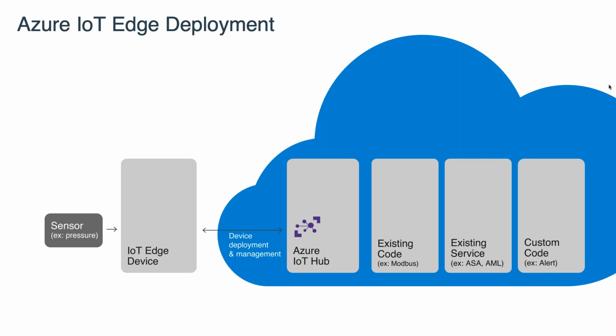After provisioning and physically commissioning the hardware, the next step is to remotely install software containers. To start with a single deployment, Azure IoT Hub has a profile for a device with a software, for example, let's say Modbus communication, has another container with Azure Stream Analytics capabilities, and then of course, custom code that the customer has developed and defined can also be created in containers.